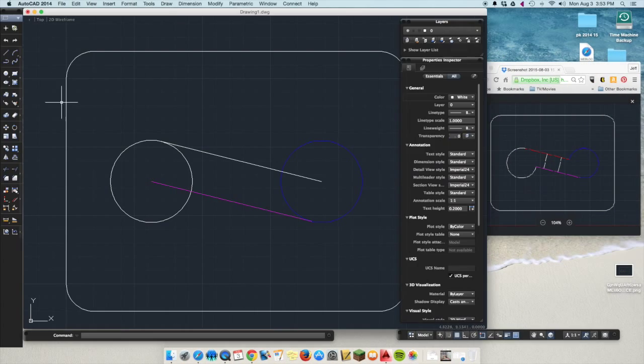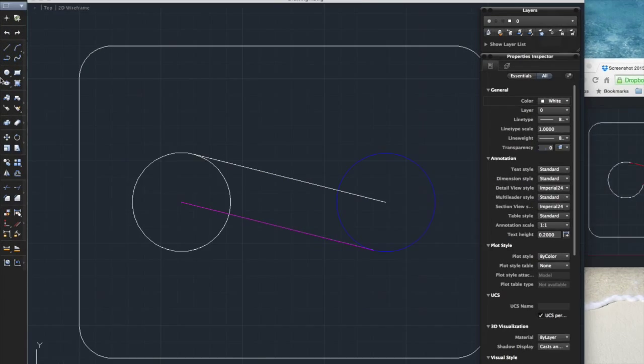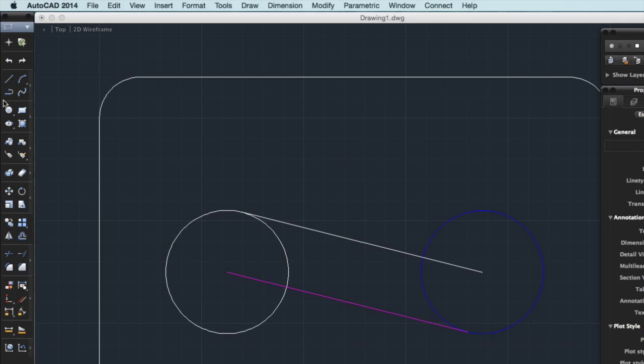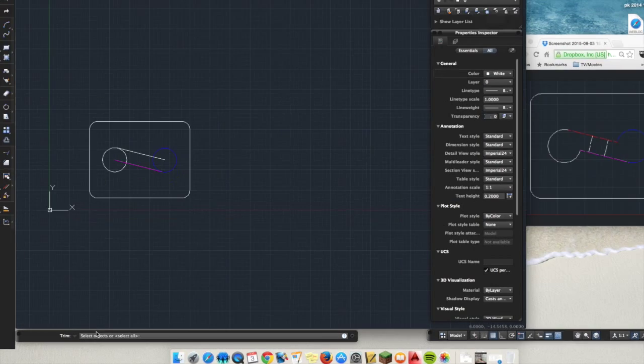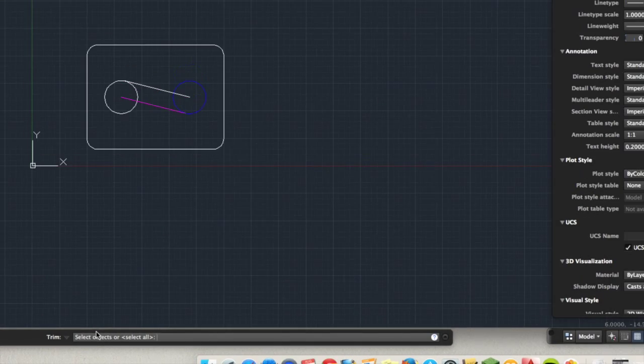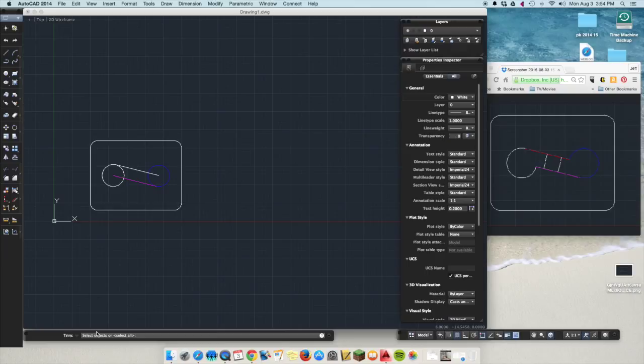Okay. There is a trim tool in the program. If you follow my mouse, in the tool palette, way down, there's a triangle that has a slice through it. If you go one underneath that, there's one called trim. Okay? And this is how the trim tool works. Select your trim tool. Okay? You will see down on the bottom on the command line it's asking us to select the objects we'd like to trim. Here's how I want you to be thinking about trimming. When you go to cut a string in real life, first you have to find the scissors. So think of it that the first thing you do when you trim is look for the thing that's going to act like the scissors.